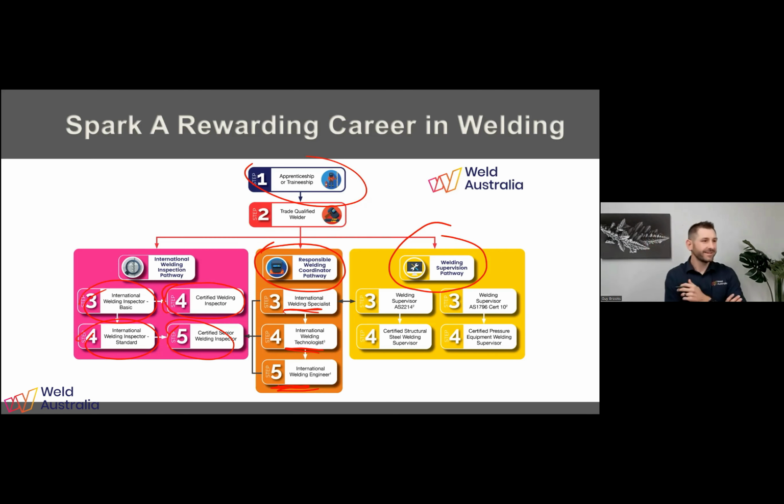What's the minimum requirements for compliance to ISO 3834 out of these qualifications? So for a company to be ISO 3834 certified, you nearly need all of these, right? From a company point of view, they'll need a welding inspector or have the provisions for inspection. If they don't have an inspector, they'll need to say we have access to this contractor or that contractor.